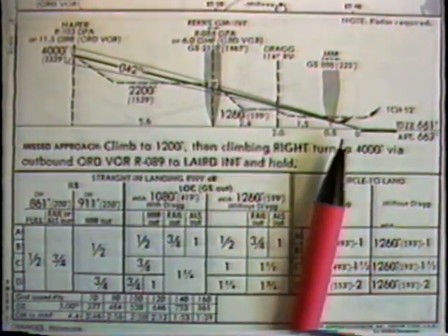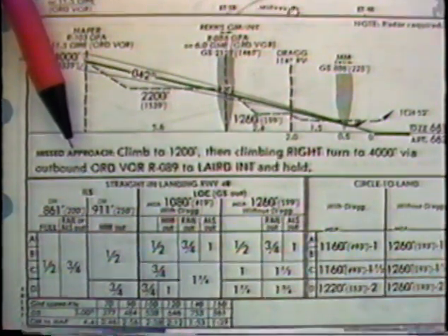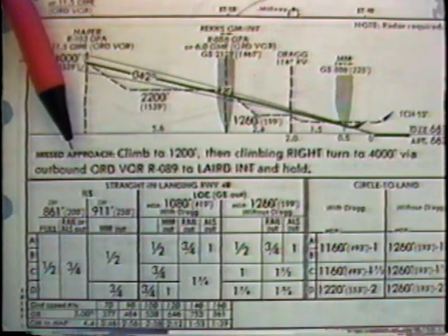Assuming the runway is not seen, the missed approach segment begins at the missed approach point. It is crucial to immediately initiate a safe climb away from the terrain. The pilot should not have to refer to the approach plate for missed approach instructions now, but should have memorized them before beginning the final approach. While a missed approach requires an ATC report, the first priority is to climb away from the ground and begin the missed approach procedure. The radio call can safely wait a moment or two.